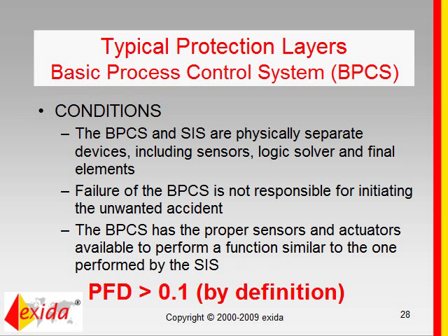It's by definition, as you can see on the slide, based on a statement in 61508 and 61511 that if a programmable electronic system that is not developed per the 61508 standard is used as a protection layer, then the maximum risk reduction that you can claim is an order of magnitude, basically still 0.1.